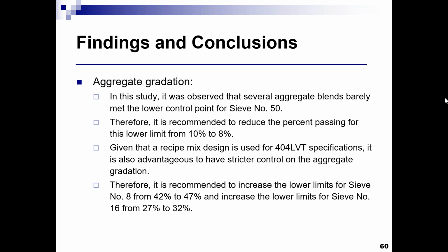this is where if any county or any agency wants to use 404 LVT mixes, it has to really be part of a comprehensive plan, because you're going to be moving from one mix to another mix. My expectation is that you're moving from type 1 surface because you observed more cracking than you would like to a 404 LVT mix. So initially, when you do the implementation, you may need to go a little bit thicker with the 404 just to basically capture some of these cracks.